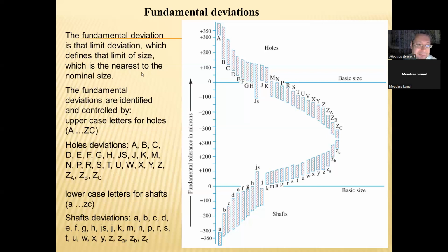The fundamental deviations are identified and controlled by uppercase letters for holes, big letters, from A to ZC. Holes deviations: A, B, C, D, and another, Z, ZA, ZB, ZC.